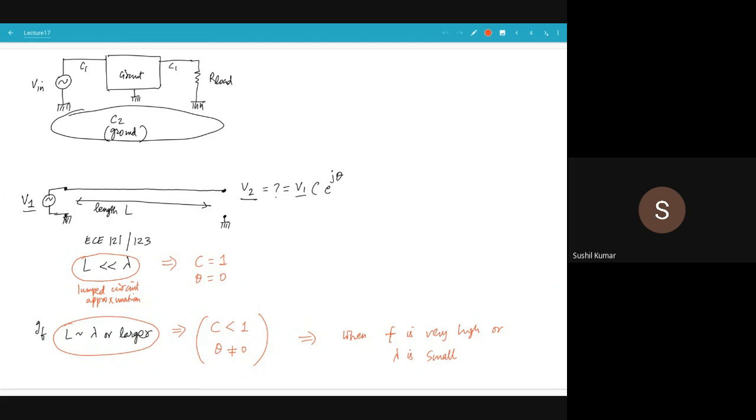If you look at its Fourier transform, this is your time domain signal. So if you look at its Fourier transform, V of f, if this is f, and you're transmitting just this on and off voltage signal on a wire, this will be around 1 gigahertz and maybe have some sort of signal like that. So if you're going 1 gigabits per second on a wire, your frequency components are at that frequency.